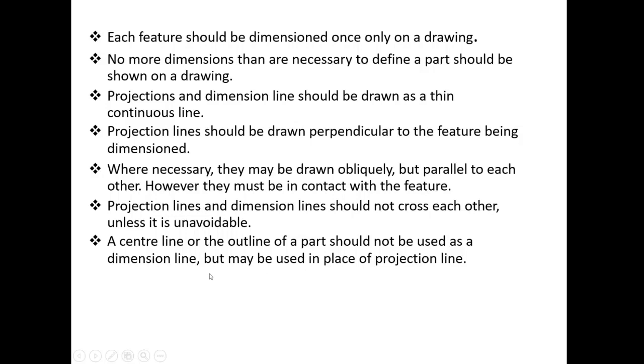Also we have seen that center line or outline of any part should not be used as a dimension line. A separate line by using the projection line should be drawn to give the dimensions. But this center line can be used as projection lines.